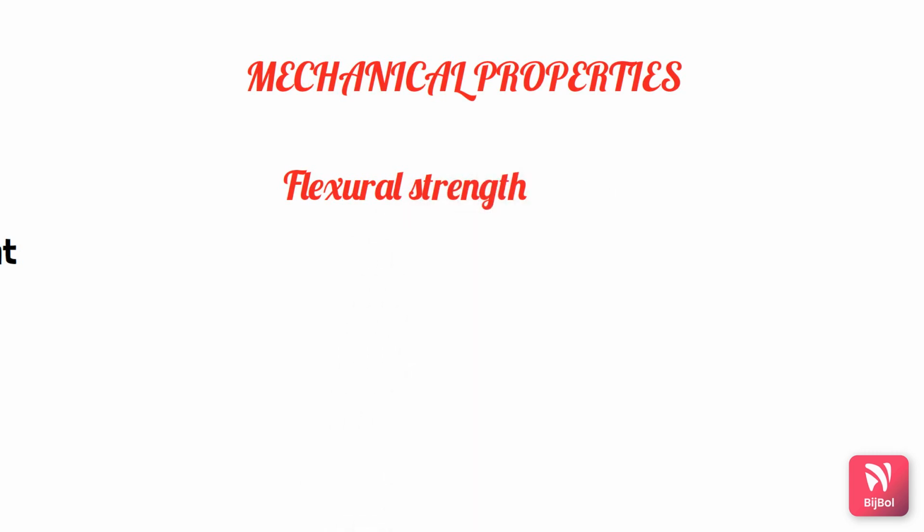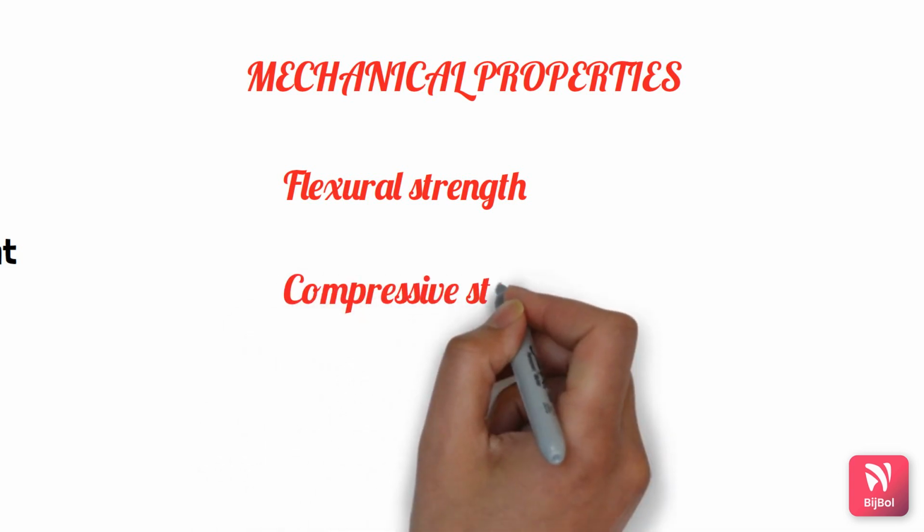The flexural strength of the various composites is similar, although the microfilled and the flowable composites exhibit 50% lower values when compared to the hybrid and the packable composites due to their filler content.